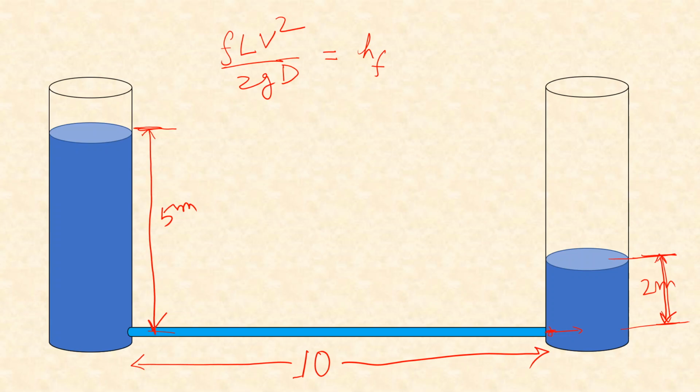Now we also know that while entering this pipe at the entry point, there will be some loss. This loss is because, let's say this is the tank, here you have all the water. Then as water enters this pipe, it will not enter smoothly. Very near this entry, water will start flowing in this direction, and as soon as it enters this entry cross section, it will converge a little bit, and then it will fill up the whole pipe.